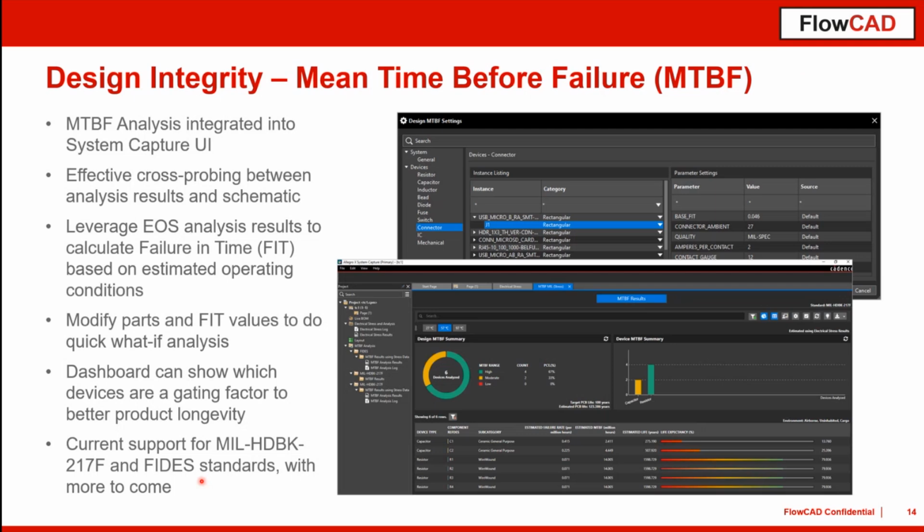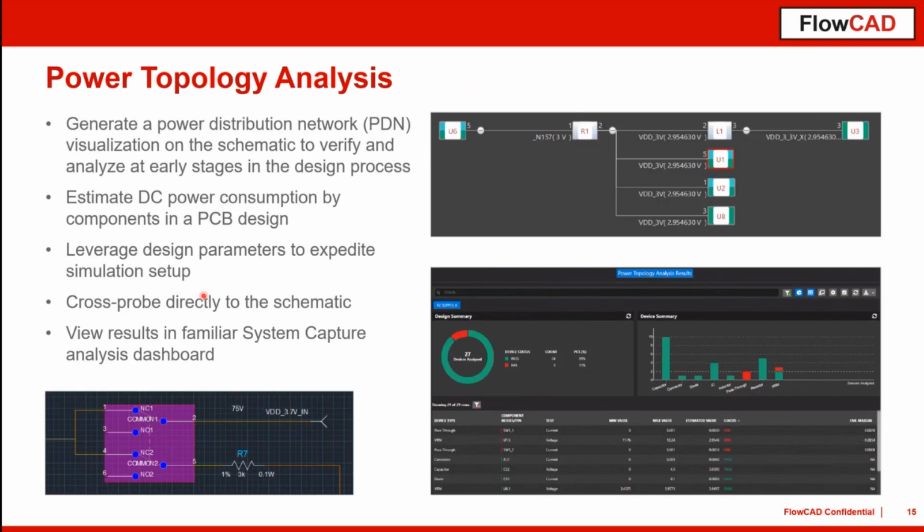For sure, you need some preparation inside of the library so that you really get meaningful analysis results. You also have to know what you are doing when running this simulation, and know how to interpret the outcome of the simulations. But if you are familiar with MTBF analysis, then you will like this because it's, again, directly built into System Capture. You don't need any additional tooling for that analysis anymore. So everything is in one UI in the meantime. The same is valid for power analysis.